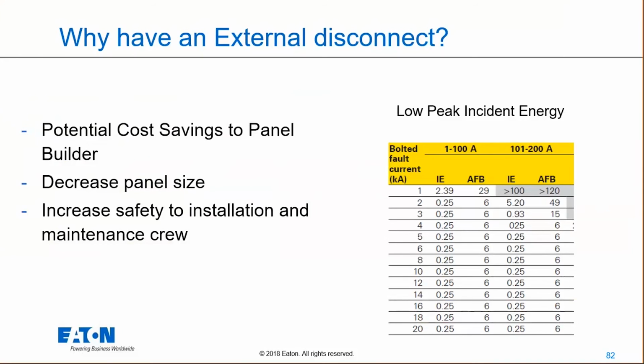If I get permission to work on that panel live, the fault current and the overcurrent device are protected by my fusible disconnect upstream, class J, 200 amps and less, because many enclosed systems, industrial control panels, fall into 200 amps and less.